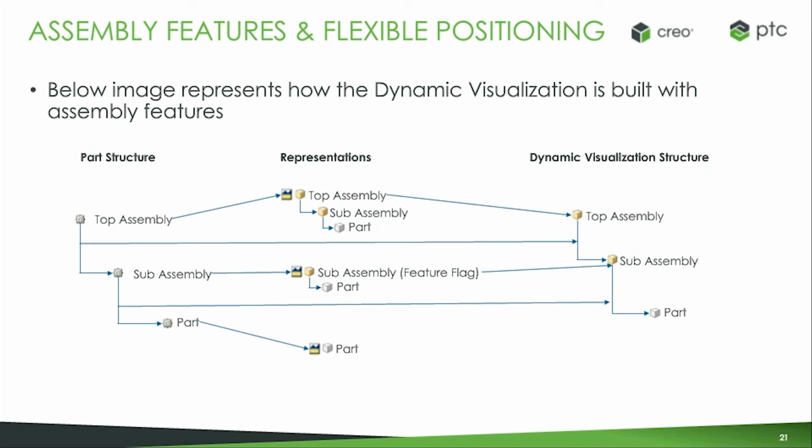So this is why it's important to make sure that you're publishing. If you have these scenarios, this is all tied to publishing. And if you haven't republished it, you may not be seeing that here recently. When we see this flag, we'll still use the position from the database, but we'll load the geometry from the subassembly's representation. And that's how we end up being able to build this out.